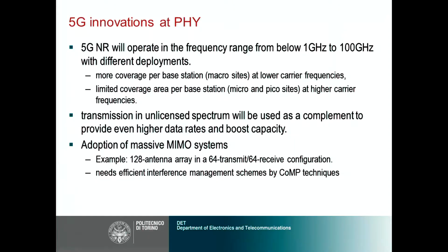There will be 64 transmit and 64 receive configurations, and we are expecting to see MIMO by UE, of course not 64 by 64 in the uplink as well, but we may see 2x2, 4x4 in the uplink as well. You'll have large arrays of antennas at the eNodeB to accommodate several parallel transmissions, even by 2x2 and 4x4.